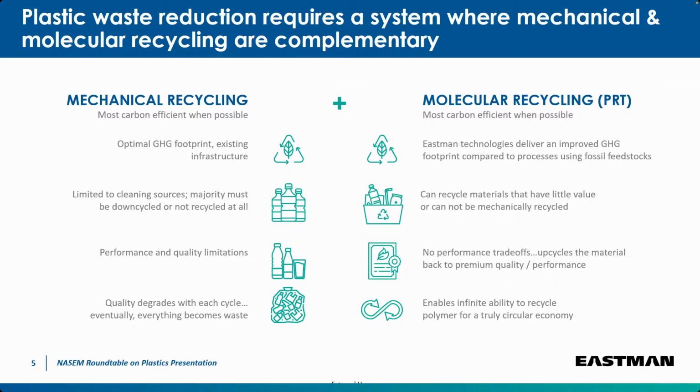This is a fantastic process to use, but there are some limitations that go along with the creation of the stream of material and making sure that all of the plastics are the same, that they're the same in terms of color and some of those, to make sure that they process appropriately. You also start to get performance limitations over time with each heat history for plastics. Every time it gets melted, it changes a little bit. And so you'll start to see degradation and some aesthetic changes that will happen each time it's used.